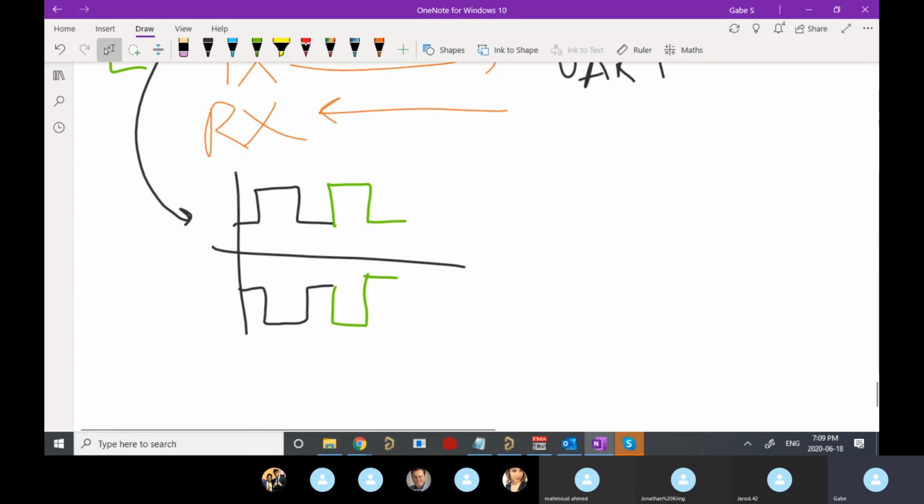And what that means is that when the slave receives them, or whoever you're talking to receives them, so if this is CAN high, this is CAN low, what they basically do is they subtract the 2. Right, so say CAN high minus CAN low equals what?